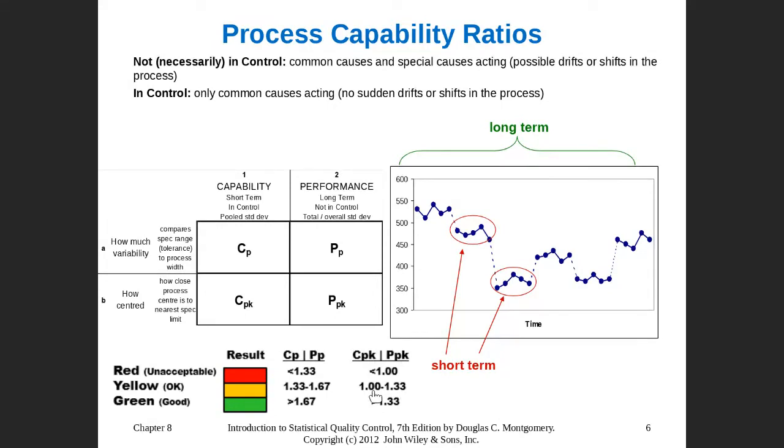It is rare to find, or we can say, that when the CPK is high, the CP will be low, because the acceptable value for the CP is easier to maintain compared to the CPK, since the CP deals with variation and the CPK deals with the shifts of the centering. But the process is acceptable when both of them are in this range. Both of them have to be in this range.